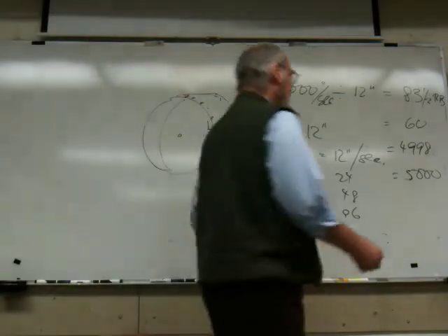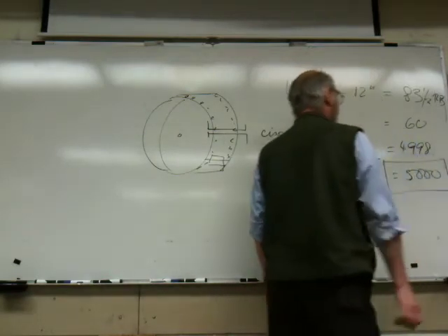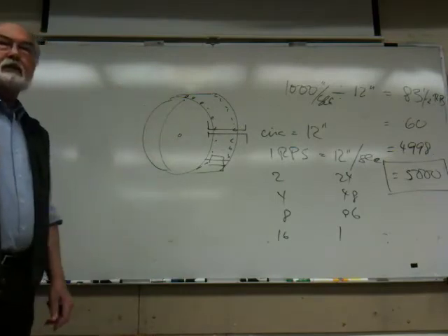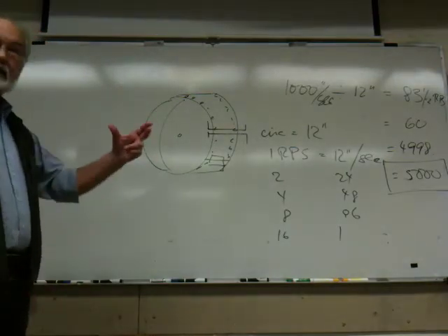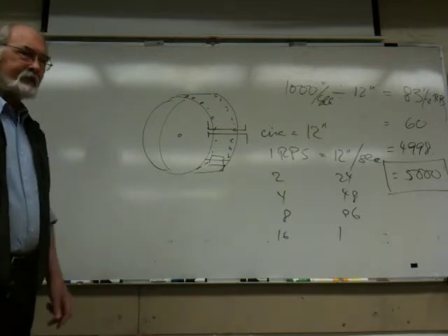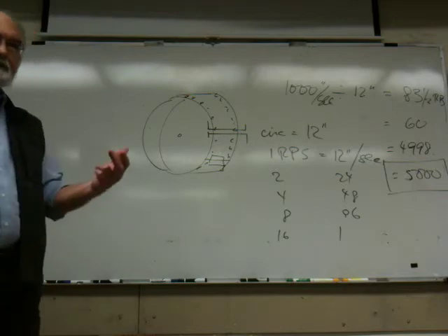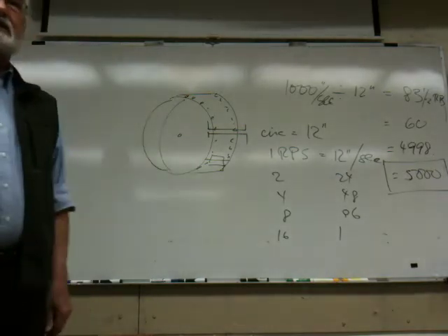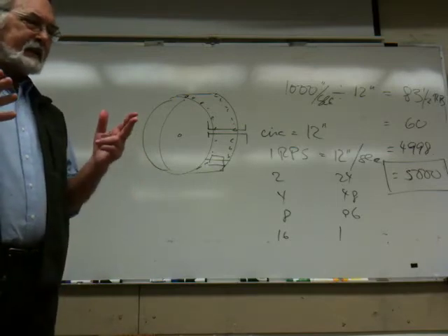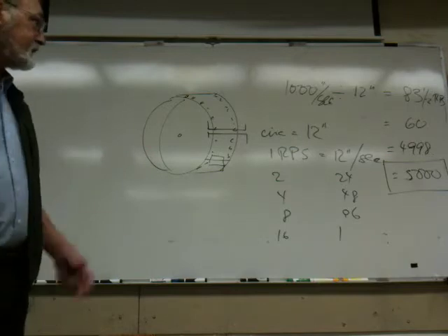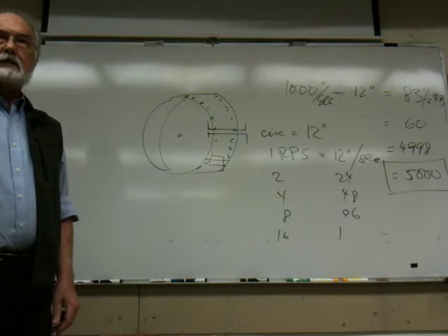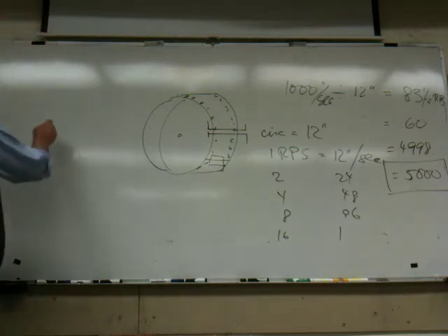So anyway, we make this drum turn at this rate, RPM, and lo and behold, the film moves through the system at 1,000 inches a second. So 1 inch will be 1,000th of a second. So now we're going to put an image of something on here. Since we're going to be measuring this bullet traveling in terms of feet per second, we need some kind of a scale of distance, because the camera, as it looks out there in space, doesn't know how big anything is. So we're going to put a scale on here.